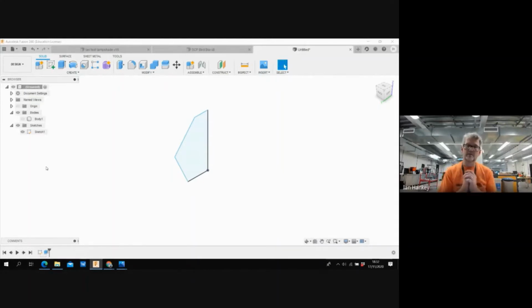I'm going to create a slightly different three-dimensional form now. And this one is going to be revolve. I'm going to revolve this shape around the axis. If I just take my sketch off and just show you the axis again, this blue line here is our Z height axis. That's what I'm going to revolve our drawing around. If I bring our drawing in now, you can see that it's actually in relation to those axes. This is why I said it was quite important.